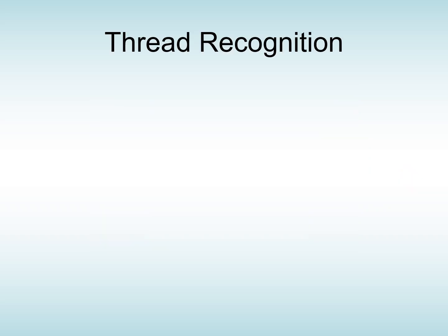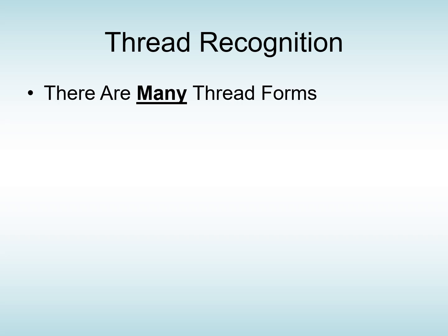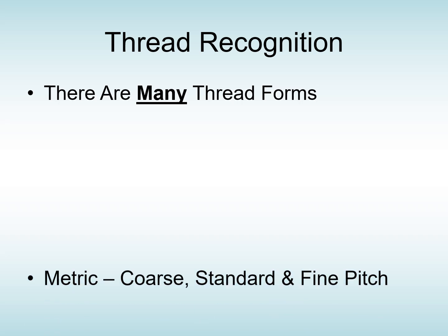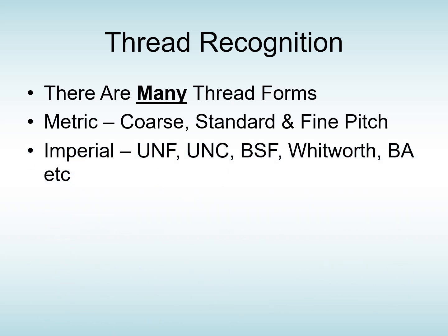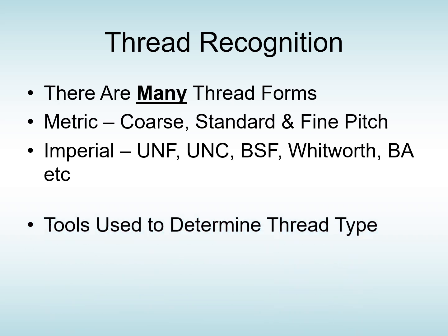Okay, thread recognition. As I said before, there are many, many types of thread forms out there. The metric, for example, you've got coarse metric, standard metric, and fine metric pitch. In imperial, you've got UNF, UNC, BSF, Whitworth, BA, etc.